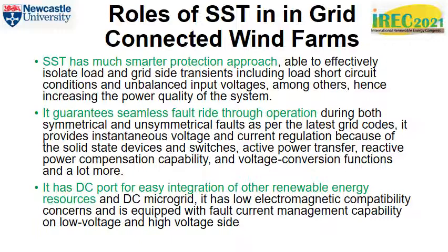Solid-state transformer has much smarter protection approach compared to line frequency transformer, which makes it able to effectively isolate load and grid-side transients, including load short circuit condition and unbalanced input voltages, among others. As such, it increases the power quality of the system. Solid-state transformer guarantees seamless fault-ride-through operation during both symmetrical and unsymmetrical fault as per the latest grid codes. It provides instantaneous voltage and current regulation because of the solid-state devices and switches, active power transfer, reactive power compensation capability, and voltage conversion functions, and a lot more.